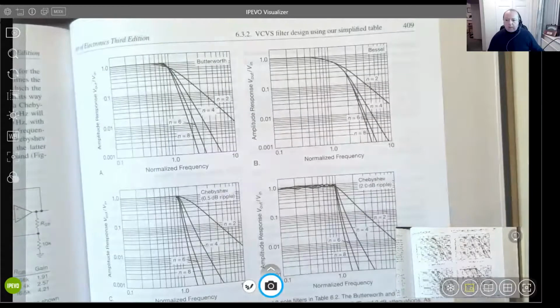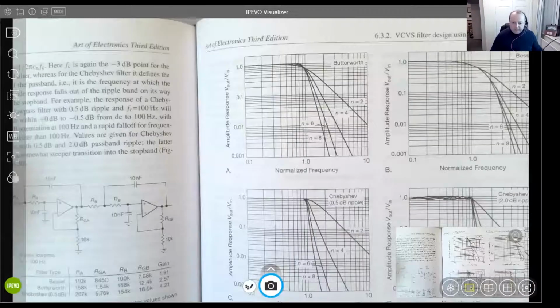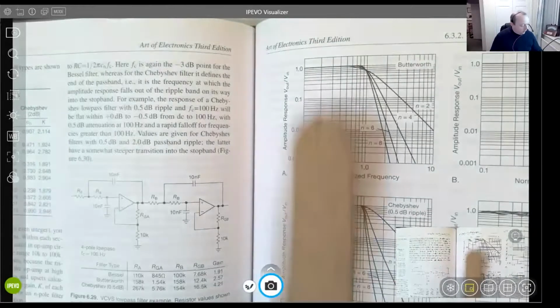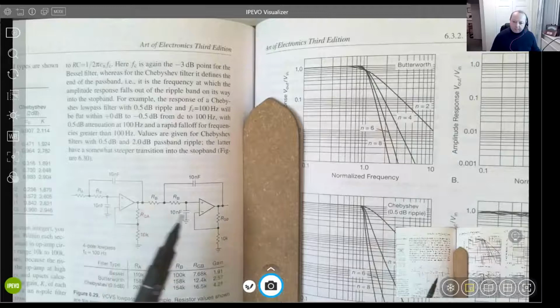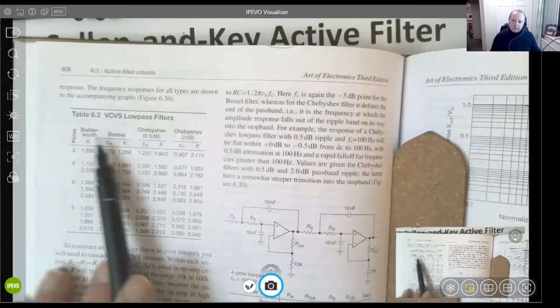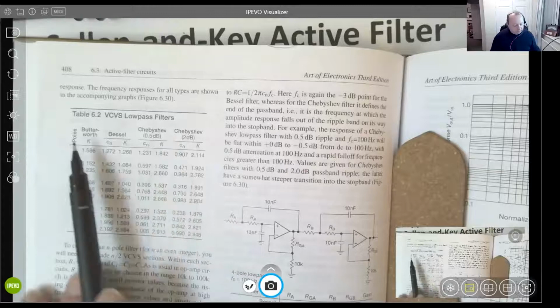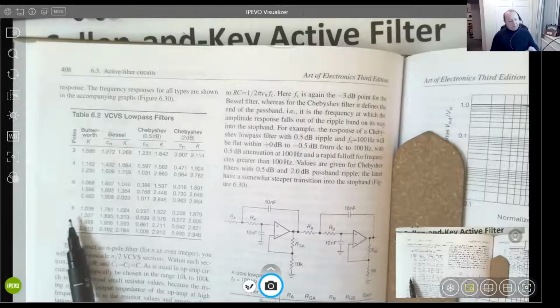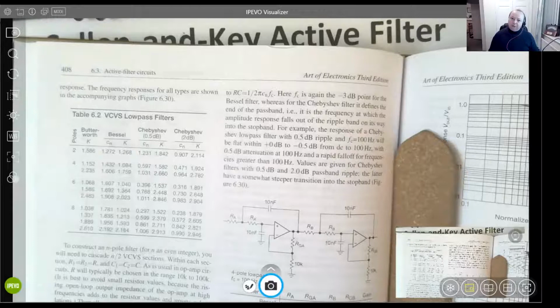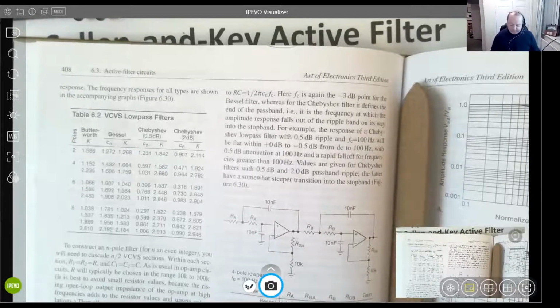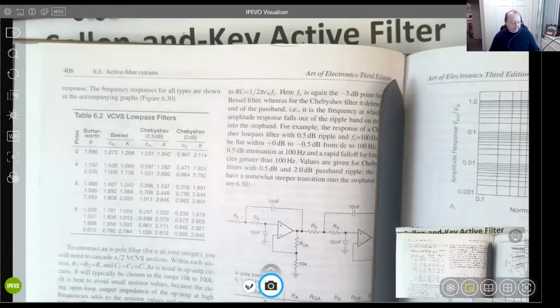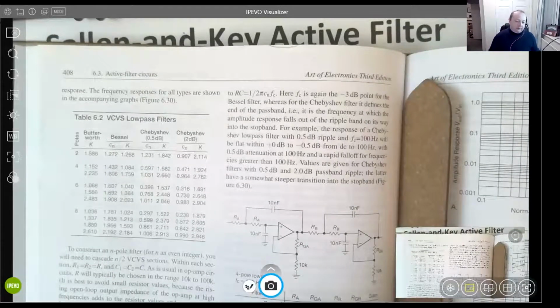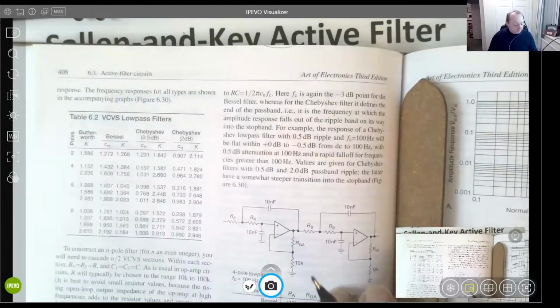There we go. Right, so if you look, you have what's called a filter order. We just had a fairly simple one, but as you can see here, you can start to cascade them together. And when you cascade them together, we get different types of filters. This one's called a Chebyshev, which is my favorite. Everyone's got a favorite filter. These are called poles, and zeros, which is complex numbers, the square root of -1. I'll share that with you another day. Try square root of -1 on your calculator, and it'll probably kick up an error. In electronics, it's fantastic, and I use it all the time for filters.